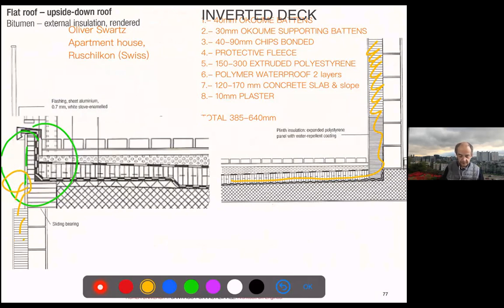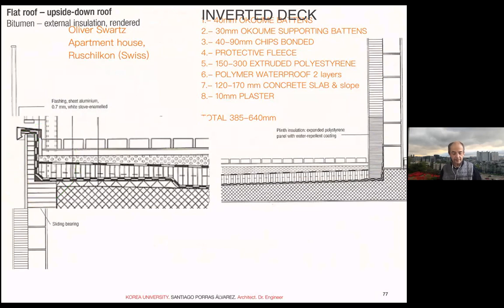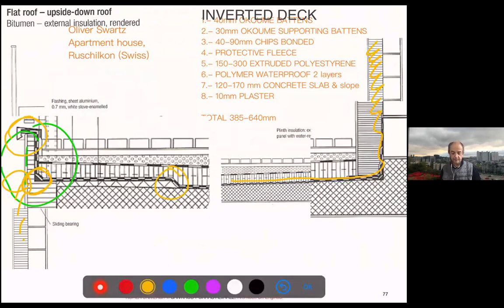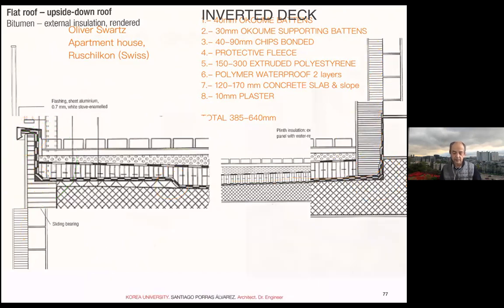And you'll see again that this is really not a standard detail, but you will recognize many of the things we saw before in general cases for roofs, right? Replicating the layers, having a soft angled bend, and then going up always at least 20 centimeters from the base.